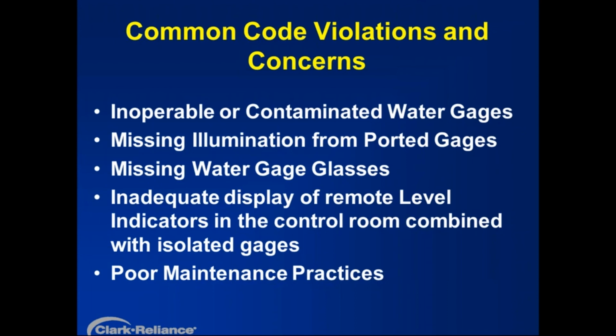Inadequate display of remote indicators in a control room combined with an isolated gauge. What I mean by inadequate display is the need for an operator to strike a key for that information to come up on their screen. That would be, as we said previously, inadequate.